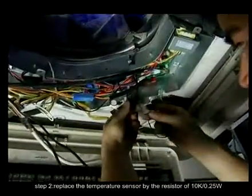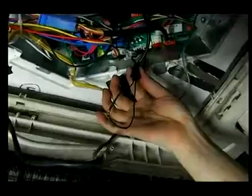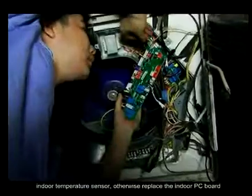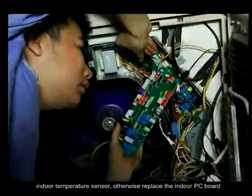Step 2. Replace the temperature sensor with a 10K per 0.25 watts one. Then check if the malfunction disappears or not. If the malfunction disappears, please change the corresponding indoor temperature sensor. Otherwise, replace the indoor PC board.